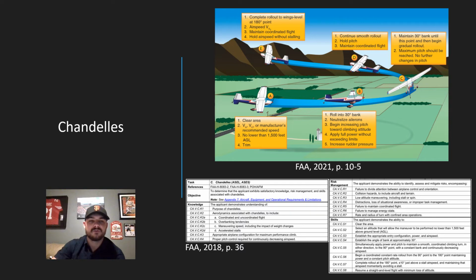too low of pitch during recovery resulting in high airspeed, control inputs not being smooth, not staying coordinated, stalling, beginning steep turn rather than climbing, not scanning for hazards, and primarily using instruments rather than visual references.